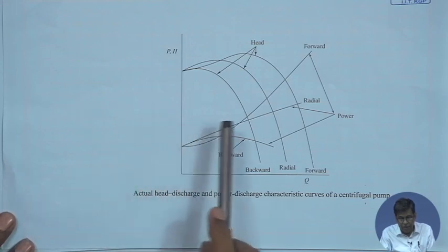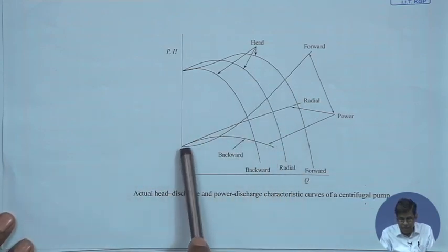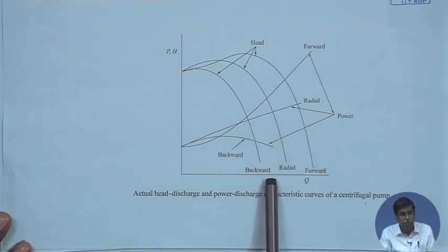But in case of the other two types of blades, since the power is monotonically increasing with Q, if we employ a motor rated at design condition, then at off design condition the motor will be working at part load, that means it will be always underrated for a time. If we purchase a motor rated at the off design condition, that will be a loss of money actually. Then if the design condition is met, it will be overrated and there is a chance that the motor may fail.